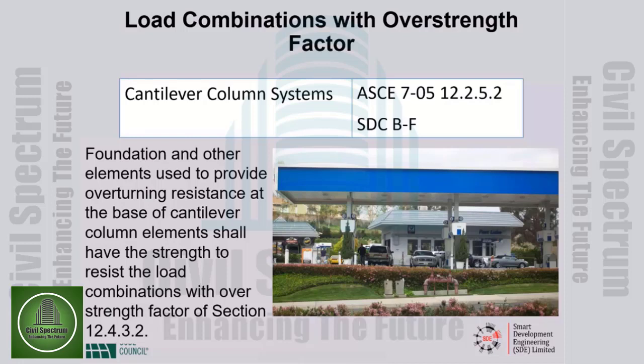They must be used where required by ASCE 7. They must not be used when not required by ASCE 7. The second part is as important as the first part. In seismic design, more is not necessarily better. You cannot just willy-nilly decide to use special load combinations in the design of your favorite structural members. That will get you into trouble. Okay, so use them where required, do not use them where not required.